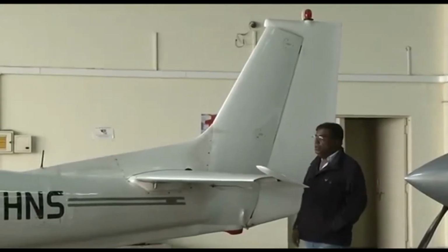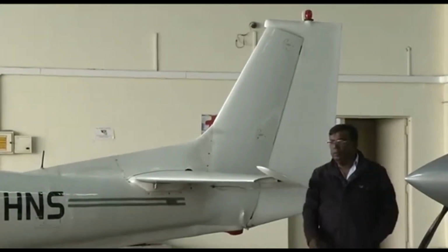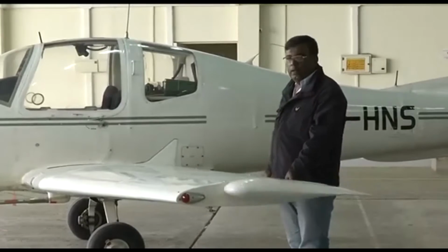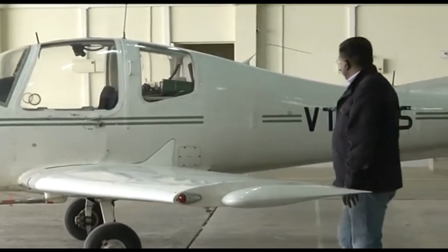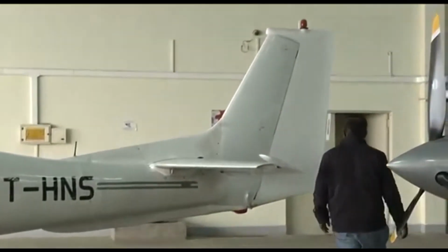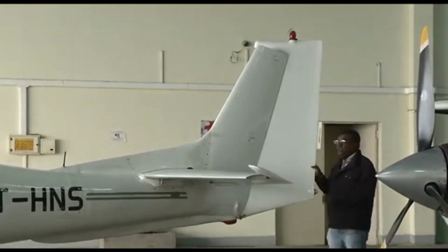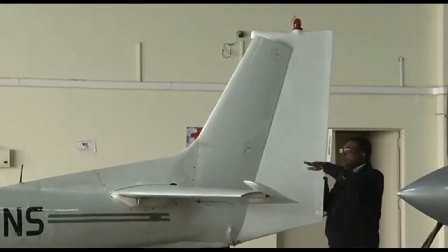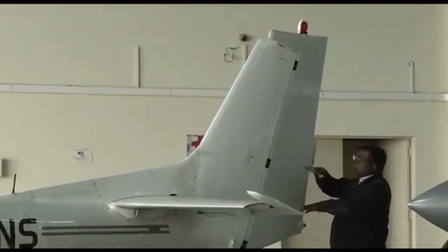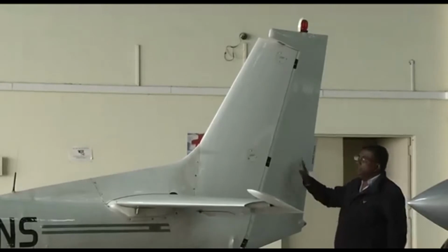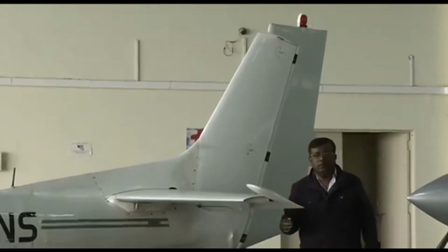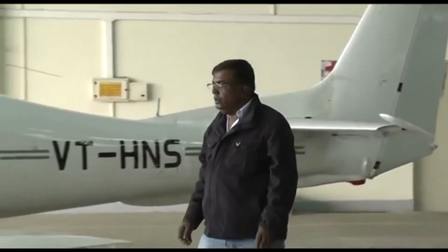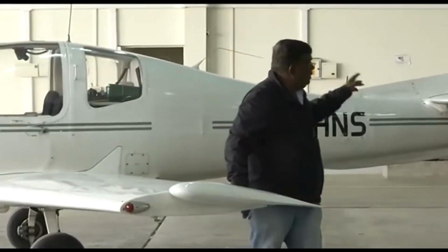And for lateral control, you have the aileron, which is here. This is the aileron. You are familiar with it. This is the aileron up, aileron down. And also we have a rudder. If I turn the rudder like this, it will give a force in this direction that will take the airplane towards left, yaw the airplane towards left. If I do it like this, the airplane will be yawed like this. Okay? So these are the control surfaces for lateral control, primarily the aileron, which is here, and the rudder, which is there.